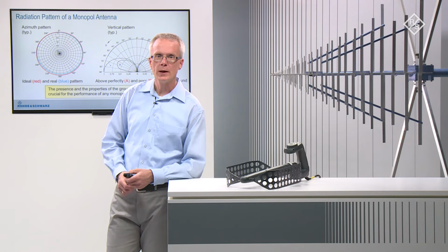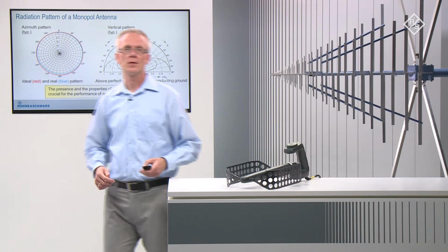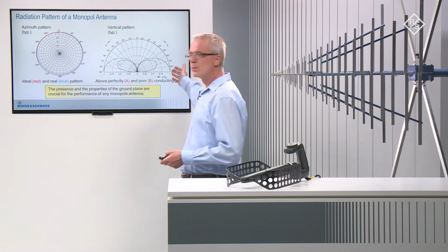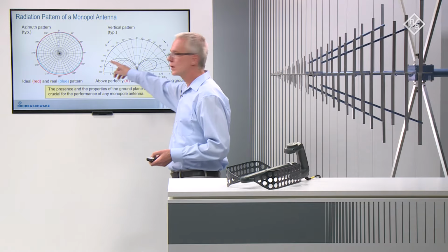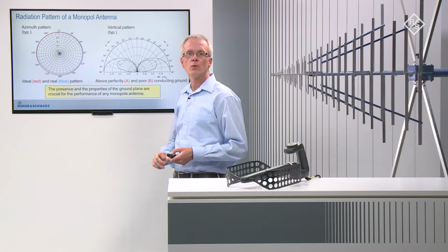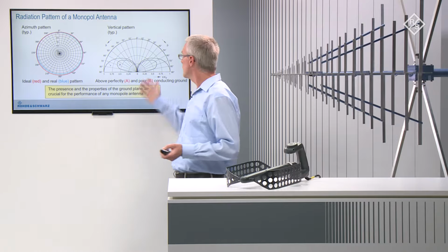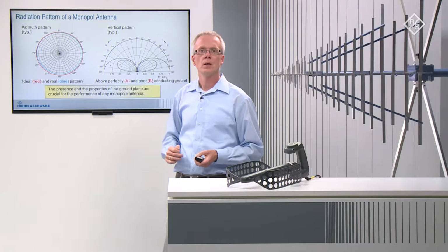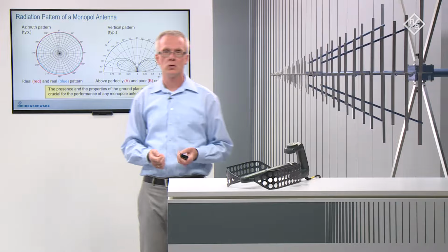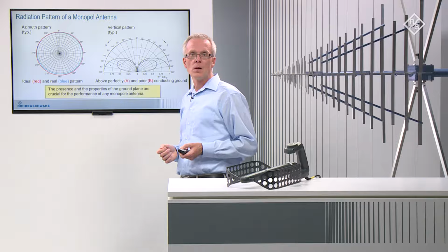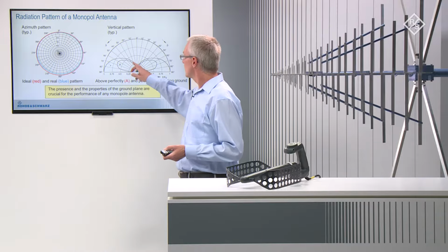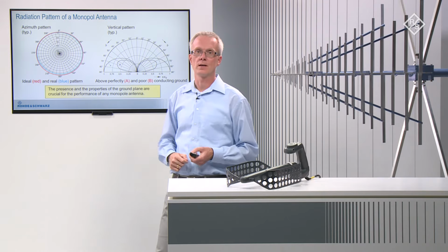The radiation pattern of the monopole is shown in the diagram on the right. It shows two curves, A for perfectly conducting ground, which is hardly achievable, and B for poor ground, which shows reduced amplitude and consequently less gain, and it is also visible that the main lobe is at angles significantly above the horizon.